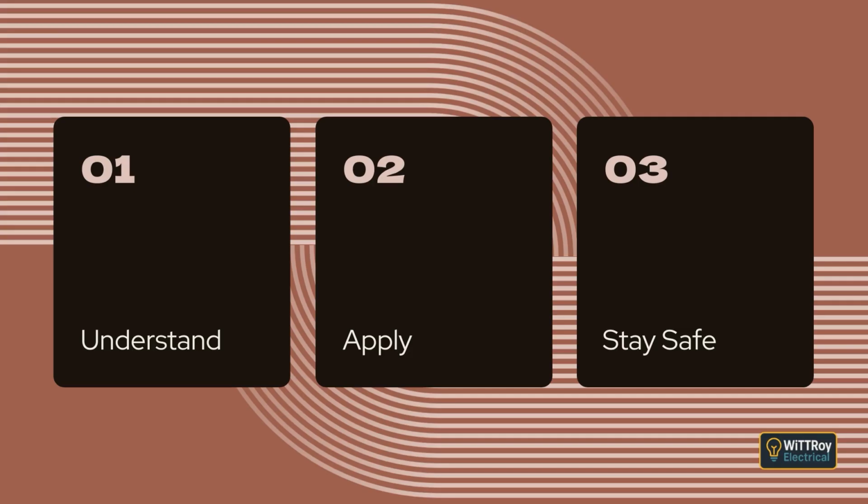Table 3.7 gives the minimum separations. The exact numbers vary depending on the service, but the key idea is that low-voltage electrical wiring must be kept enough distance away from other underground services so that damage or faults in one system do not affect the other. Some exceptions apply, such as when services are installed in the same trench but kept in separate enclosures, or when conductive enclosures are bonded to the electrical earthing system.